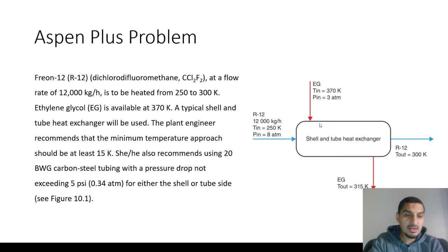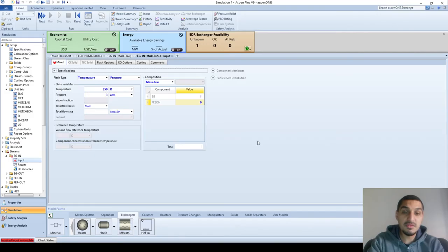And the same here, it is M, which I don't know, multiplied by Cp, which I don't know, multiplied by delta T, which is around 50. It's 55 degrees. So the delta T is almost the same. And from this, I can tell that the ratio between the flow rates would be inversely proportional to the ratios of the Cps. So if I can get a sense of the ratio of the Cps, I can use a number that is logical for the flow rate.